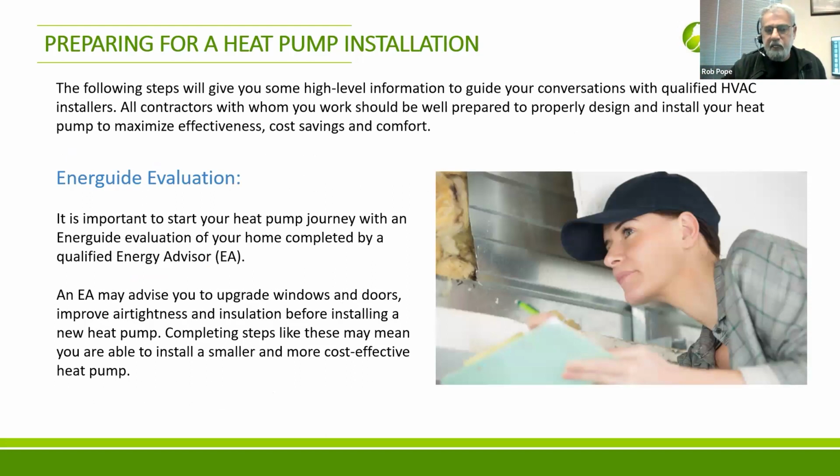An energy advisor evaluation is pretty straightforward. You do a blower door test, you find out how drafty the house is, but you also investigate the level of insulation, basically the energy performance of the building as is. A good energy advisor will give you really good advice on cost benefit if you just do this to the walls or the windows or the attic or weather stripping, and how that will change the energy performance of the building itself.